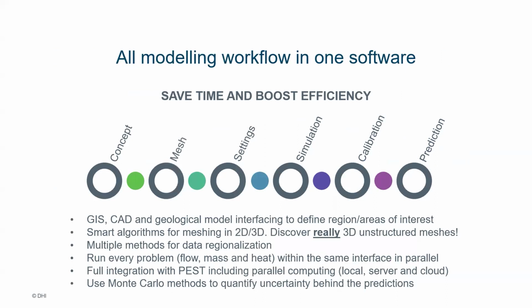At the same time, we cover our workflow from model conceptualization. This is something that we have been developing in recent years, and this year we will focus more on conceptualization in 3D, coming later with FEFLOW. We do a lot of meshes in 2D and 3D, tetrahedral meshes directly in FEFLOW. The whole simulation, calibration, and predictive uncertainty quantification can also be carried out with the software.